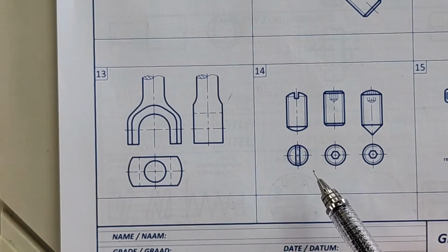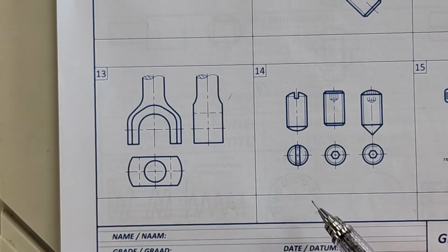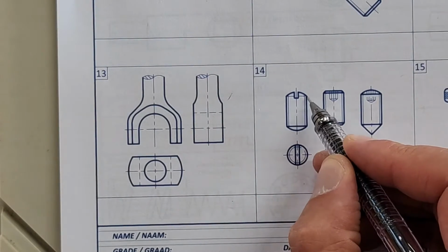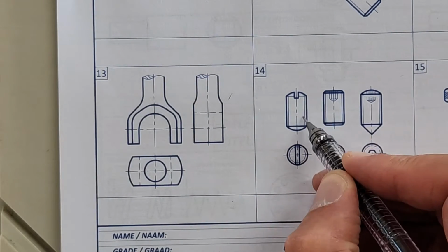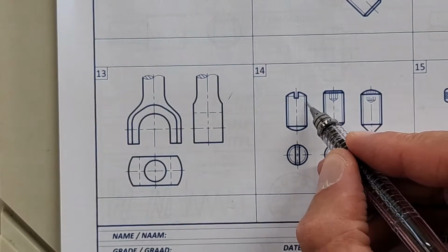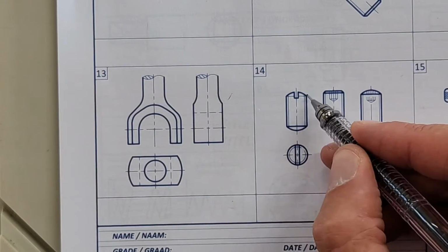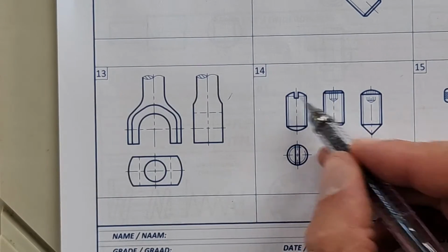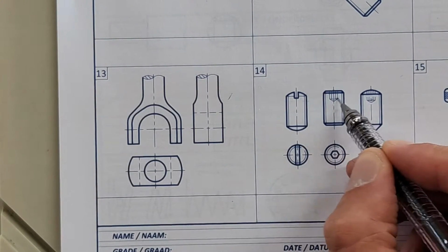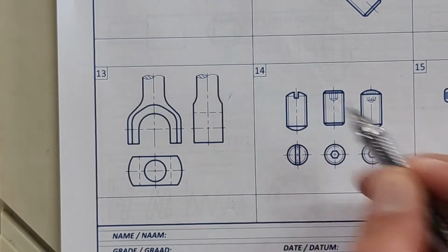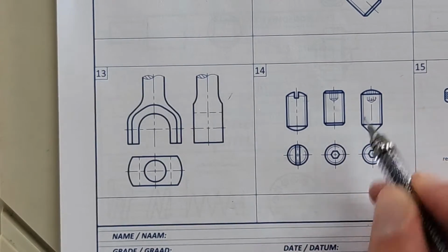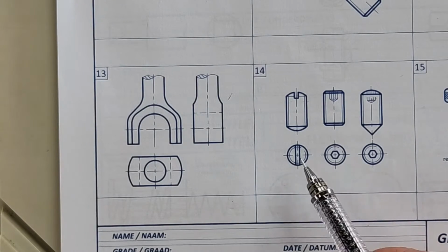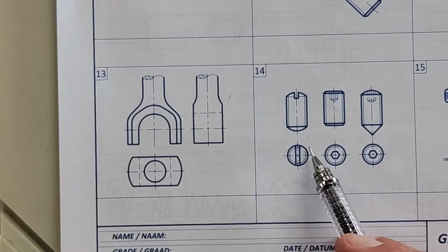Good. Then next to that, we have our grub screws, klemskroewe. What's interesting, just take a note here, there's no shoulder on them. Like your previous screws all had a shoulder. A grub screw is just straight, linear, and it's got a place for either an Allen key or some other key that goes in there, or a traditional screwdriver. Got different endings, but that's a grub screw. Afrikaans, 'n klemskroef.